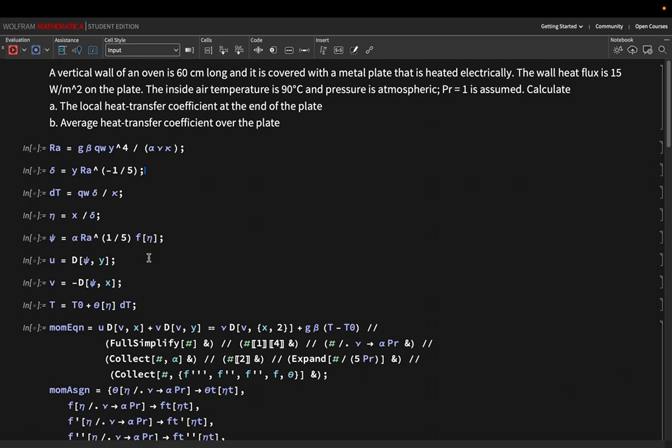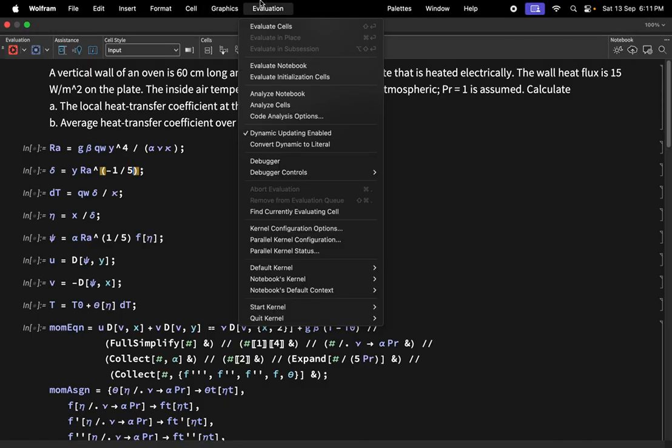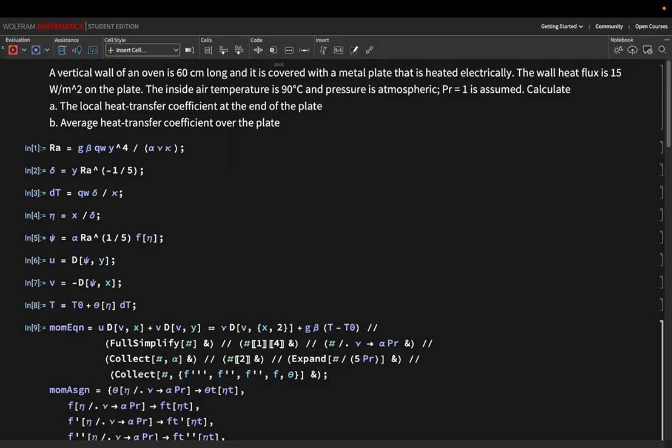If after doing all these transformations I get a differential equation of that particular form, then the self-similarity is true. For boundary layer equations, if you have attempted with 1/4, the resulting governing momentum or energy equation will have x and y terms in it. So the self-similarity is not being preserved with the 1/4 law, but if you put 1/5, then the entire equation will be independent of x and y, and it will only have eta in each.